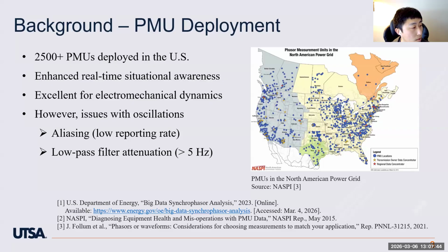The second issue is low-pass filter attenuation. PNNL's report, the last reference on this page, shows that dynamics above 5 hertz will be distorted by the PMU.